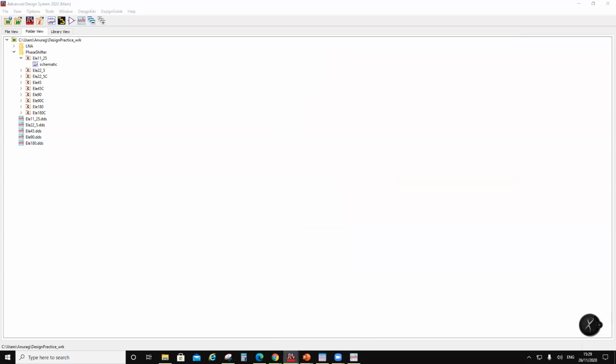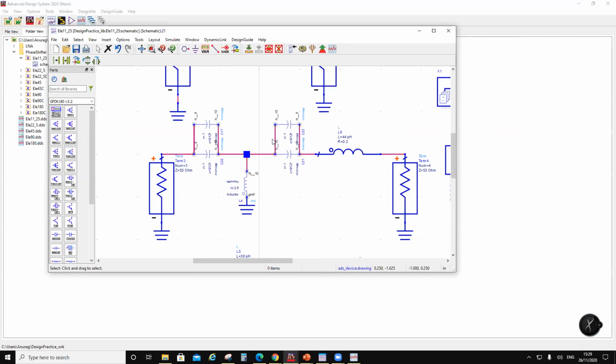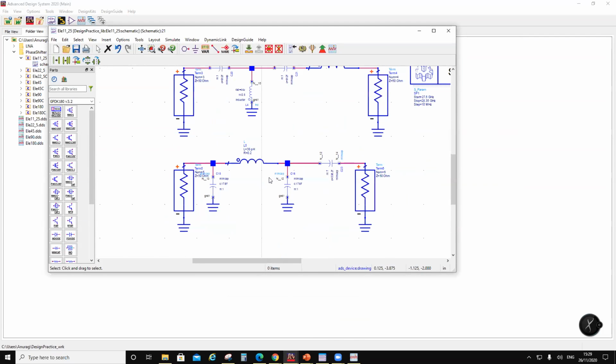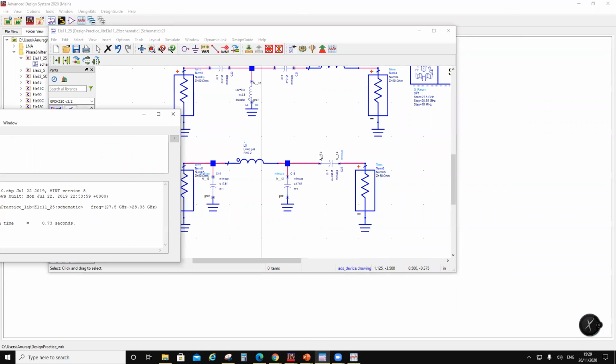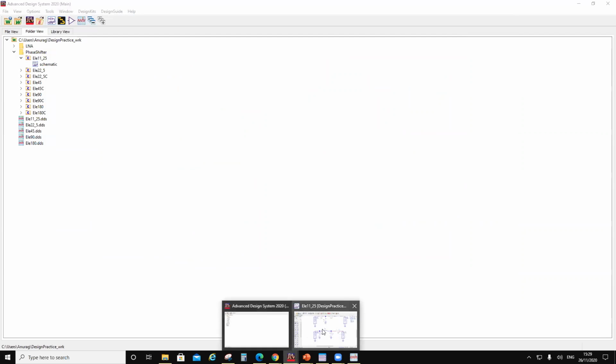So over here, these capacitors have to be reduced. Okay. And this inductor has to be increased. Okay. So of course you can spend some time with this and try to see what is the best you can get in terms of return loss, still maintaining your 25.25.